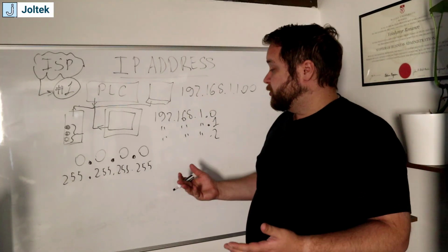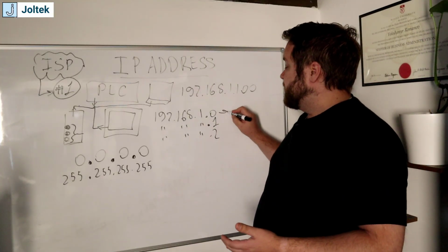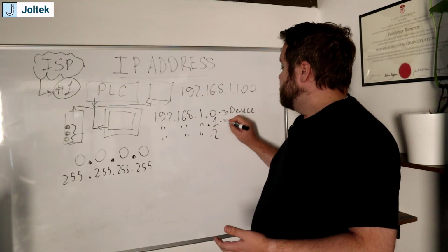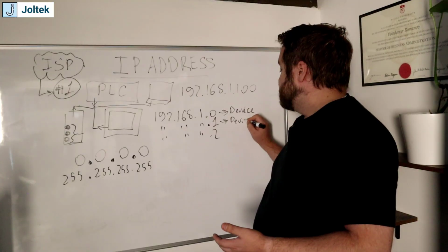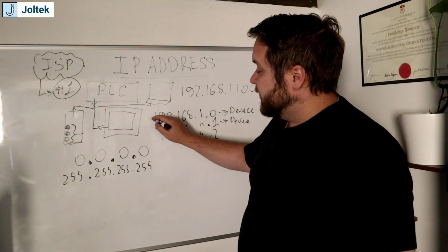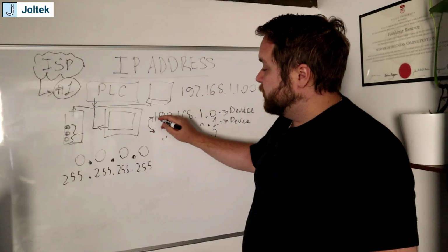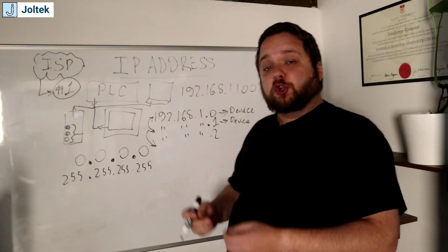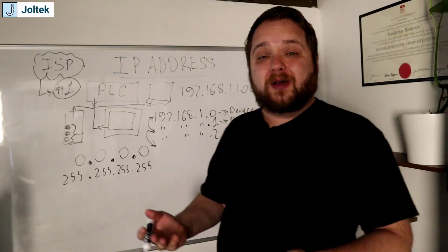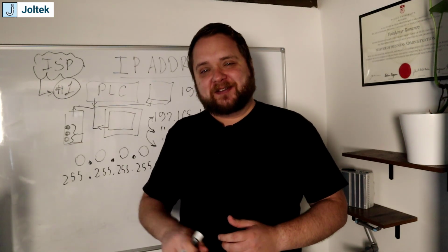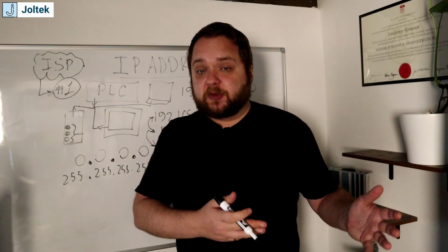So basically what we're trying to do here in assigning these IP addresses is to allow the devices to be on different, which is a requirement, IP addresses, so that they can send packets between themselves, right? So this could be your PLC, this could be your HMI, this could be a VFD, but they're all able to communicate on the same exact subnet, right? And subnet is something that I've called out a little bit in some of the previous lectures.